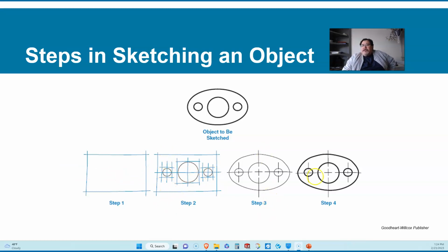Then in the other direction, I'll get the spacing right and draw vertical lines to get an idea where the centers are. So I'll get the center lines of the circles, and then continue by drawing the squares to establish the size of the circle so I can complete those circles. And then finish the trace out by leaving the locations of the center lines, and then roughly trace out the location of the ellipse, and then darken everything into its finished product there.